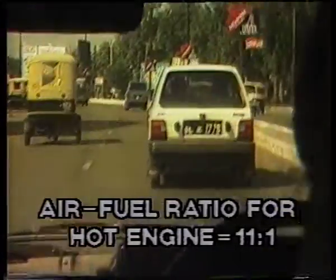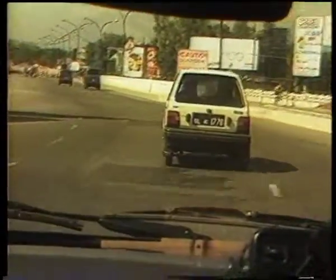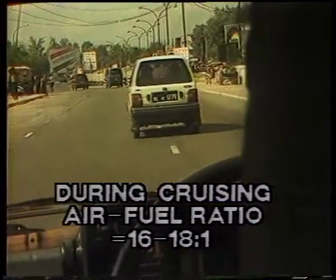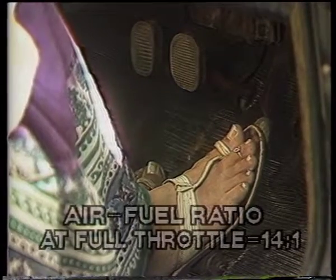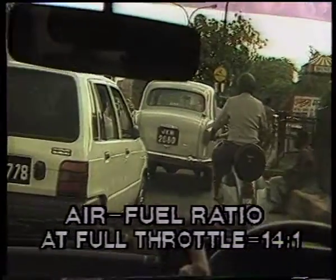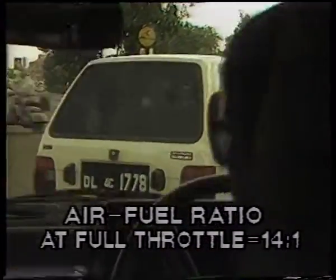When cruising, the mixture should be as lean as possible for economy, while maintaining smoothness of running and freedom from hesitation and surging. At this stage of cruising, the air-fuel ratio is between 16 and 18:1. Maximum power at full throttle, regardless of engine speed, always demands a richer mixture than when cruising at part throttle and is generally in the region of 14:1.